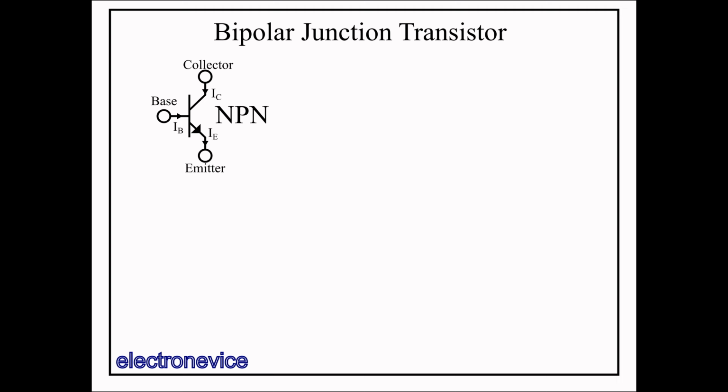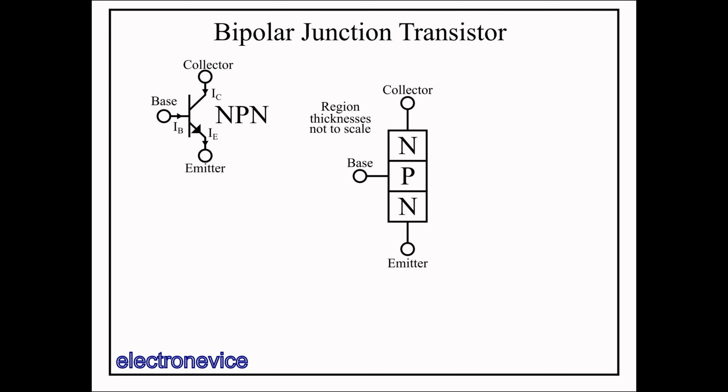The transistor is made up of three distinct semiconductor regions that are all contained within the same semiconductor crystal. The regions have the same names as the terminal names. The collector is a lightly doped N-type semiconductor region, the base is a lightly doped P-type semiconductor region and is quite thin, and the emitter is a heavily doped N-type region. So we see that while at first glance the structure looks symmetrical, the significant difference between the collector and emitter doping concentrations indicates that it is not.